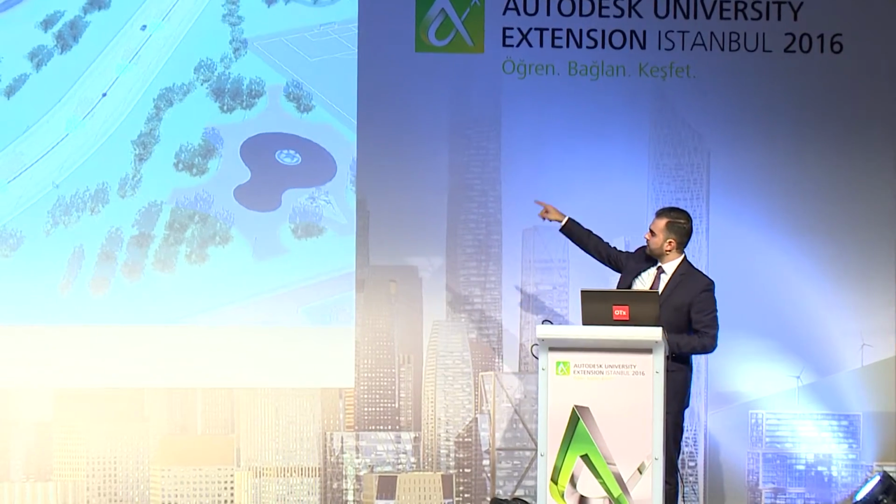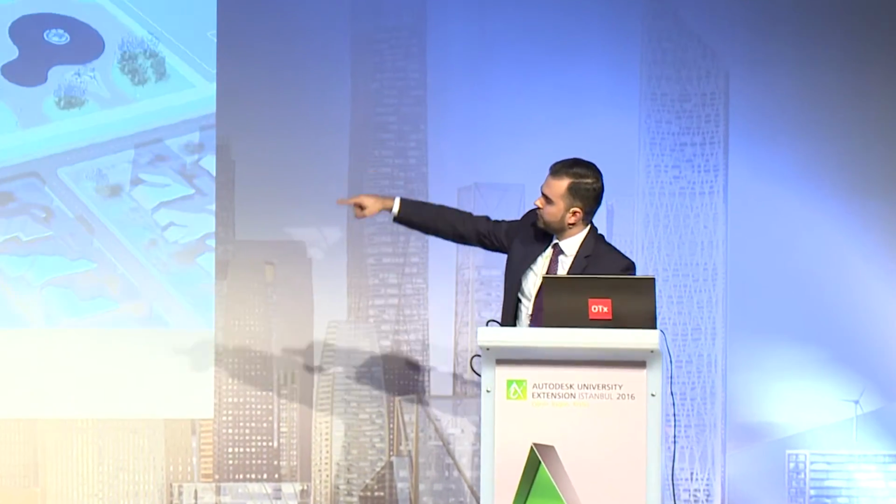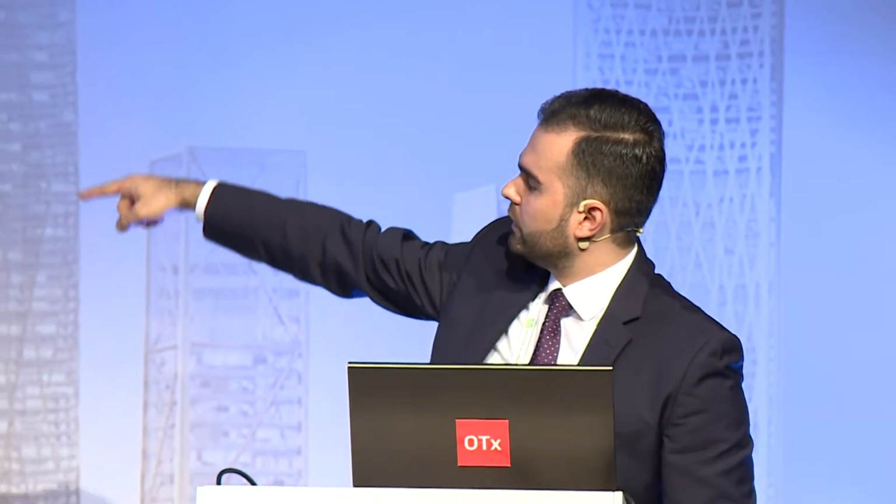Okay, this is just an example of InfraWorks. So I'm laying, there is a certain road, a highway, for example, a 2-lane highway, and I'm opening it in Civil 3D. You will see that it will open instantaneously. I just have to select the area of interest, open the InfraWorks model. I'll be able to pick what data I want to import. Here we've got the terrain, for example. If we have watersheds, we have the alignment of the road.